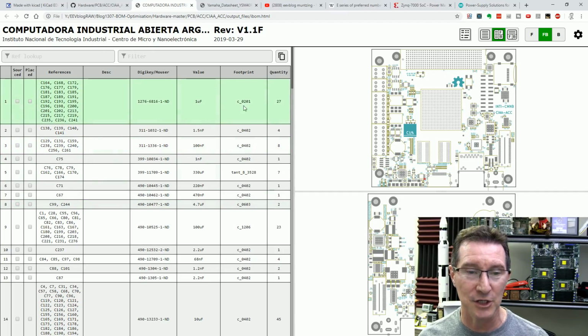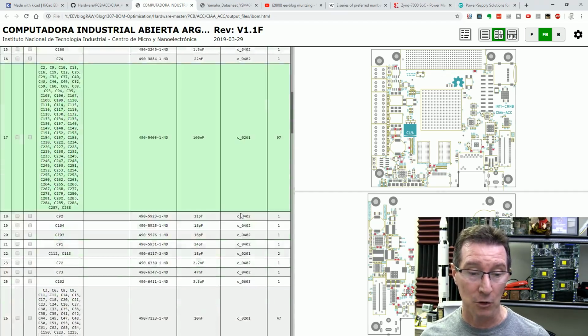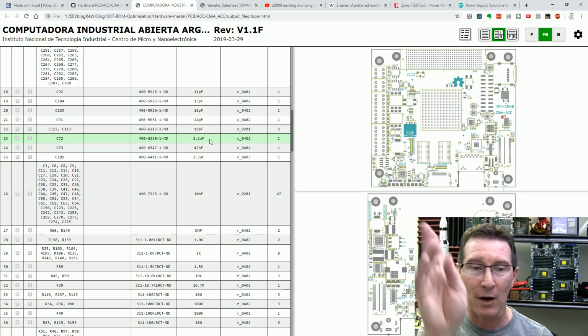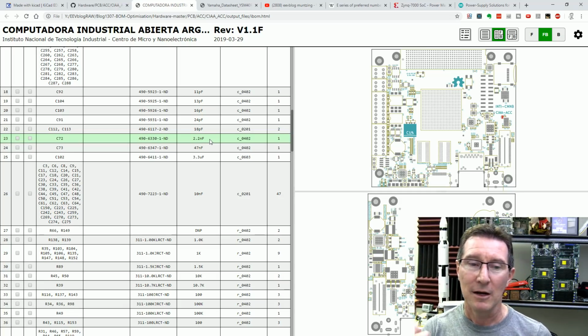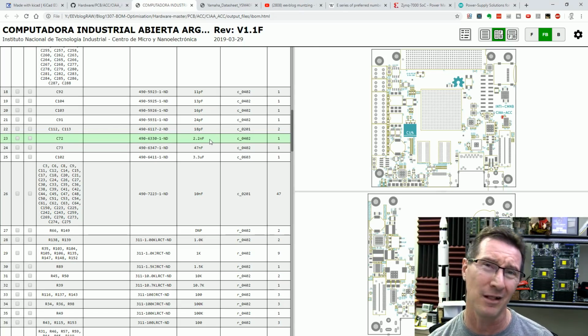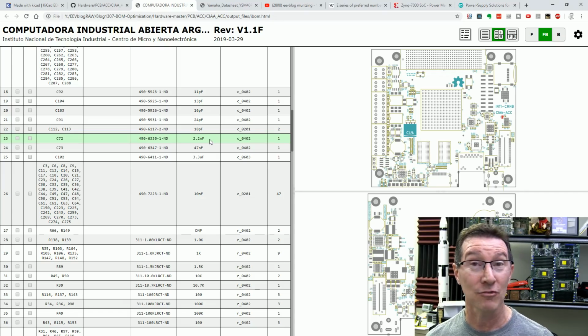So this is why, if I was designing this and I looked at this BOM, I was doing my BOM consolidation, this one sticks out like a dog's hind leg. 0201. Is it the only 0201 part? Oh no, there's another one. Okay, so they're using some others, but it might stick out, sort by package type or whatever, and it might pop out. Oh look, we're using one 0402 in this entire design. Really? Do we have to? Can't we just use an 0603, please?